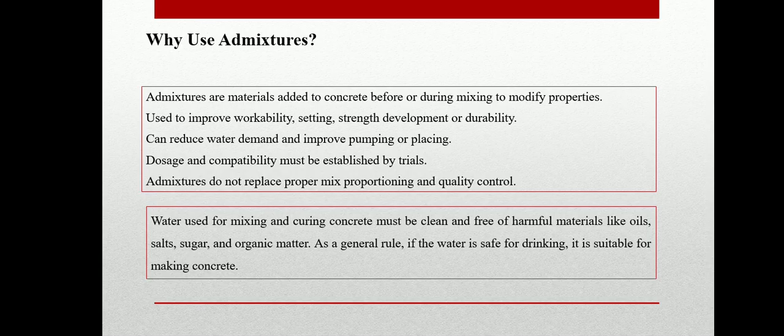But the dosage and compatibility of any admixture must always be established through trials. We should not add an admixture based on a textbook number and a hope for the best. And admixtures are not a suitable substitute for good mix design. They do not replace proper proportioning and quality control. They enhance a mix that is already fundamentally well designed.